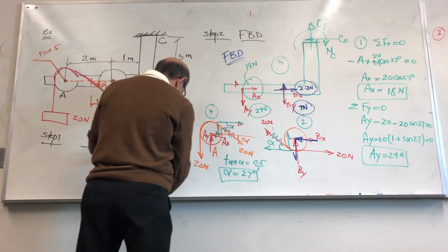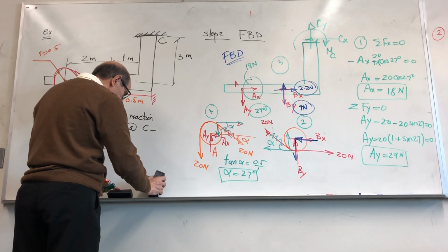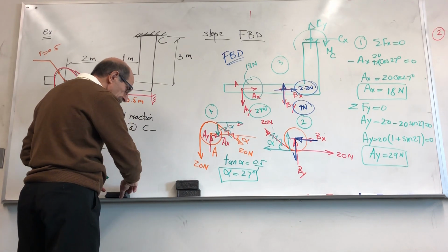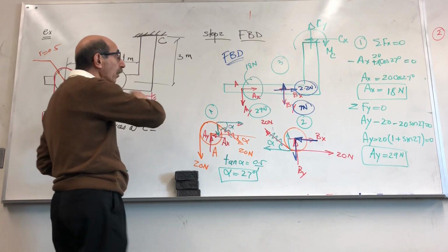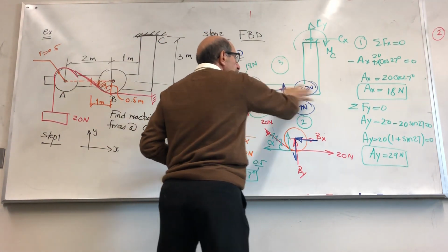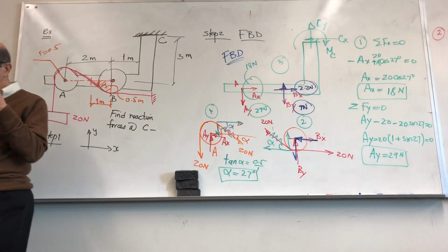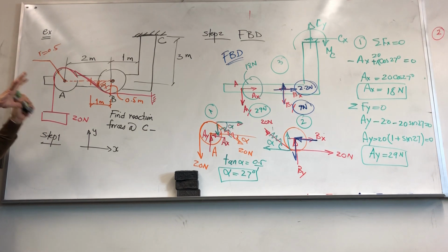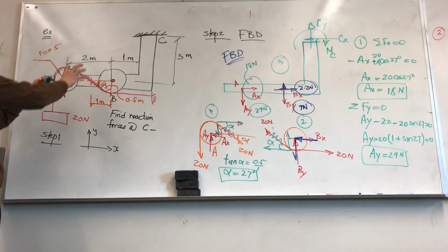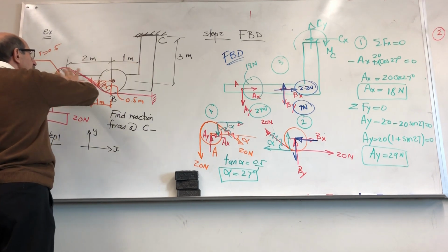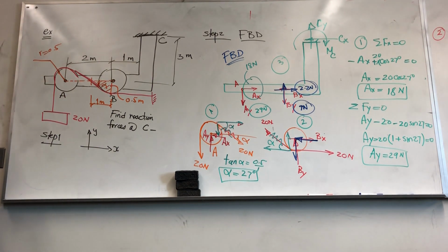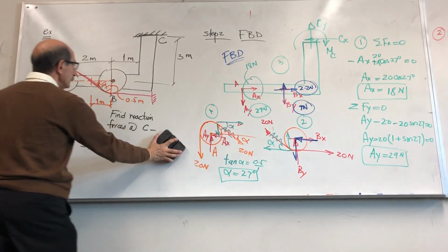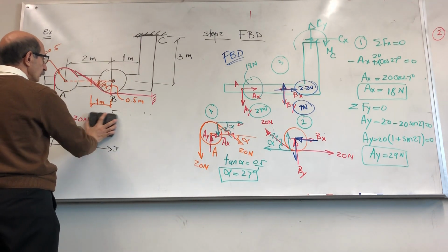I did it this way first because I wanted to just focus on the free body diagram of the structure that is our interest. So if you're isolating that structure, anything that is attached to it, I want to remove it, just focus on the free body diagram of that structure. So these pulleys, I did not consider them as part of this structure. I take them out, so the effect of taking those out means putting some forces back, which is what I did. But there's also another way that you can look at the same structure, right?